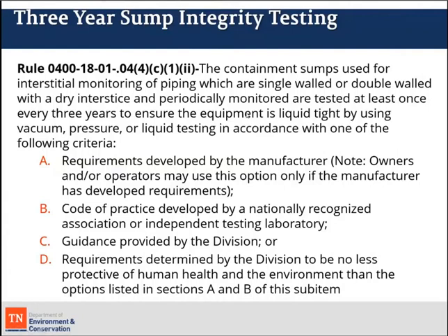So the requirements of performing these tests are set forth. You have to use a test method or a test procedure that is developed by the manufacturer and follow their requirements, or you could follow a code of practice developed by a nationally recognized association or independent testing laboratory. We utilize PEI's RP1200 as a great document. All of the testing procedures that I'm going to go over in this presentation are based upon the most recent version of RP1200.